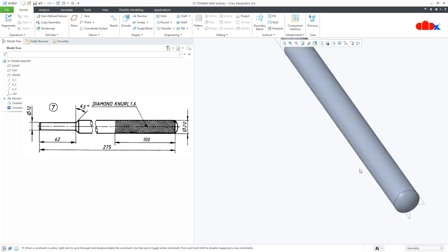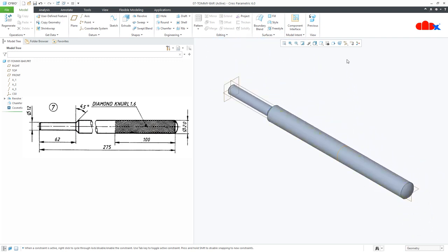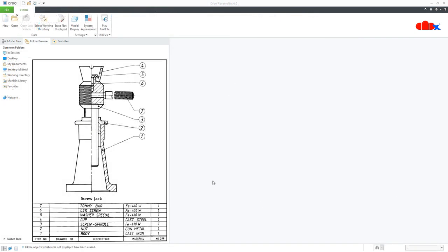So this area is the knurling area. So we don't create this knurling area as a cut feature. We practically create this knurling area with a standard knurling tool. So no need to specify any dimension for it, and that is why we don't create any feature for this. So this part is done. Now save it and close it. So all the parts are done.